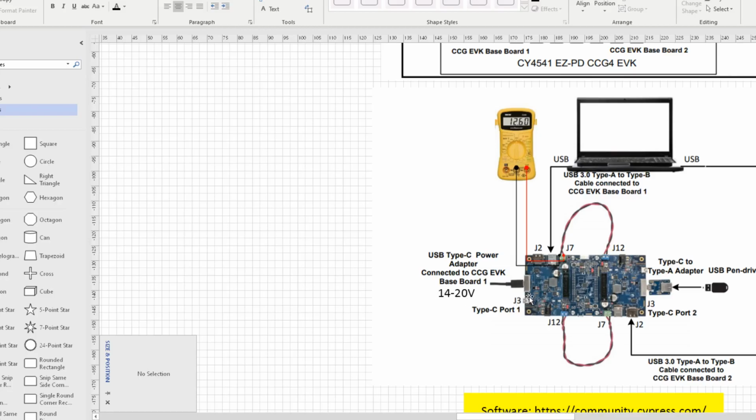Okay. And then at 14 to 20 volts, it should appear there. I think the multimeter reading is wrong. It should get 14 to 20 volts because that's the power out. It goes straight into the other side, which is powering the device. That other device says it needs a minimum of 14 volts, so I think this is a bit wrong. I think this multimeter reading is off. You've got to assume this is 14 to 20 volts, and here you get 14 to 20 volts, which then powers up this side of the circuitry, and the USB port will only request 5 volts, so that's okay.